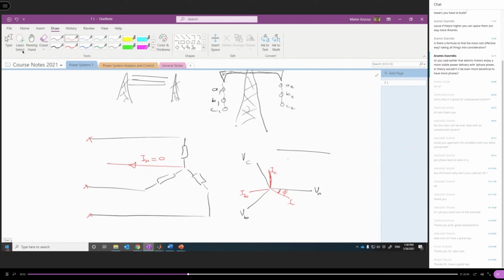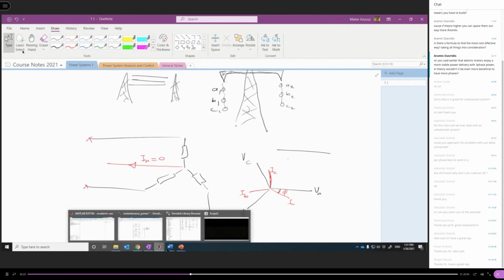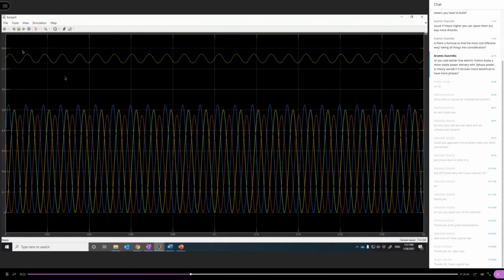But when we approach distribution systems, I mean when the transmission line is near the customers, the cities, the distribution utilities, then we need to have the neutral wire, because loads are not balanced. Loads are not exactly identical. I mean, utilities and power system operators try to balance loads, but at the end of the day, there is an amount of imbalance. And as I told you, a small variation in the voltage magnitude will create oscillations in the active power.